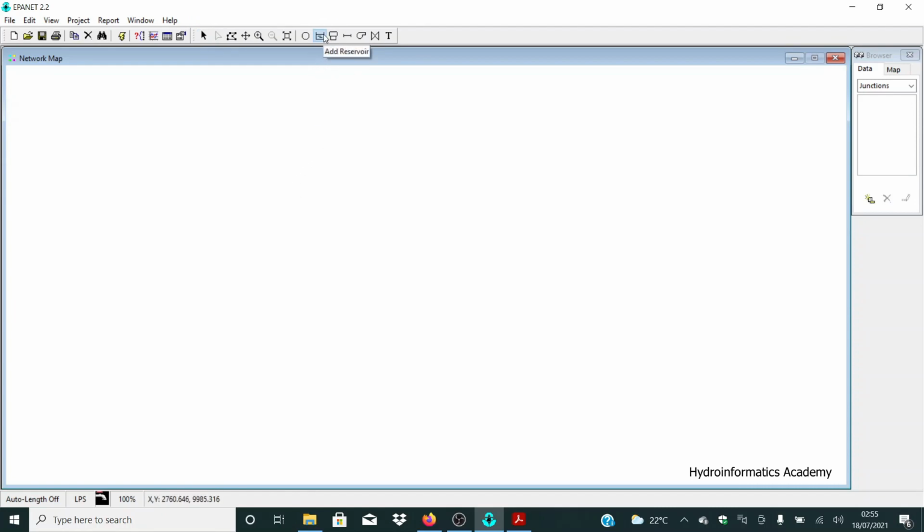So I'll just select this reservoir just to model a river. In EPANET, we model a river by using a reservoir. Then I'll insert a few nodes here, this one and also this one, and again the other junction from here, and the other one here, and the other ones in this region, and another one also in this region, and again we have some water distribution points.